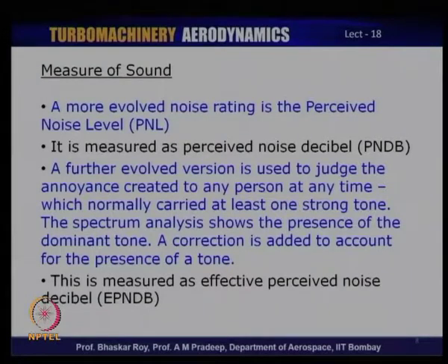Some of these can actually be captured in the spectrum analysis of the noise meter, and then a correction can be added to account for this extremely annoying tone that is present in the noise, and then this corrected noise is referred to as effective perceived noise and is measured as effective perceived noise decibel. So, EPNdB is what nowadays noise is being measured in, especially with regard to aircraft engine noise.